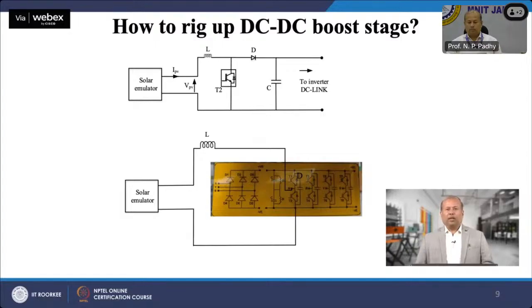Let us say we have 4-leg inverter so that the legs consisting of R, Y and B phases are utilized to rig up 3-phase 3-wire inverter, and this will be the DC-AC stage. Now, to build DC-DC stage, we can use the unused 4th leg as mentioned earlier in my previous description. And currently we can see the actual DC-DC boost converter circuit which has been shown here, and how to build it using this IGBT stack along with the DC-AC inverter.